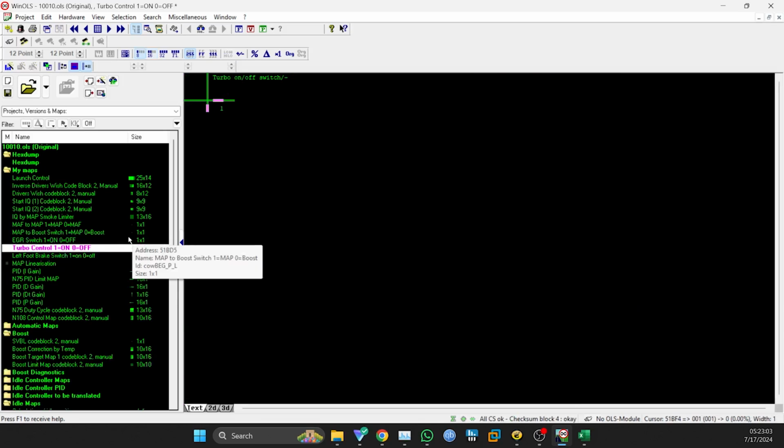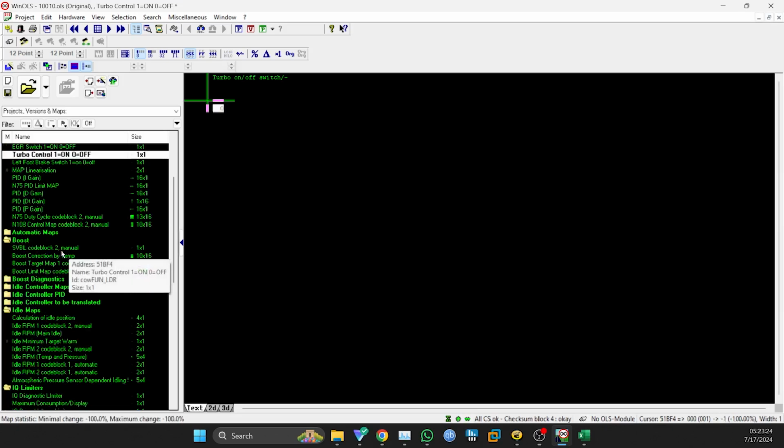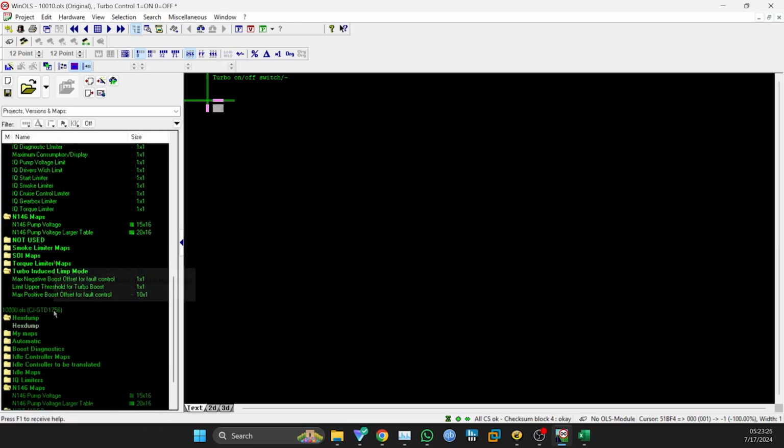Turbo control. This is if you want the turbo to be controlled by the ECU, i.e. you have an N75 that works an actuator that works the VNT or VGT mechanism on the turbo. If you want to use a wastegated turbo, you're going to turn this off, right? So we'll turn that off, and then you're going to have to go and make the adjustment.